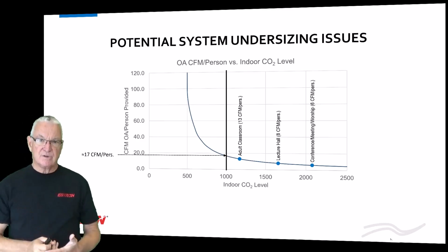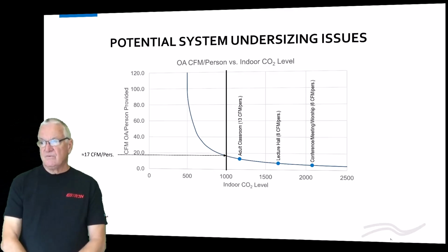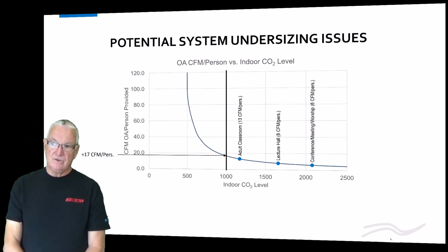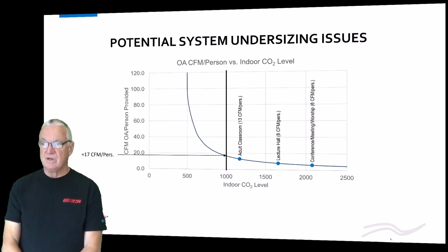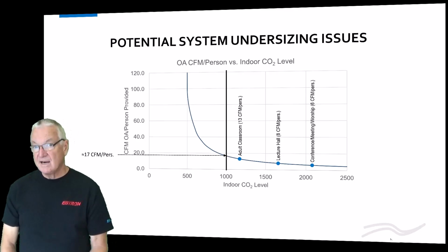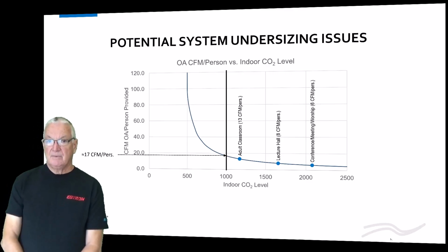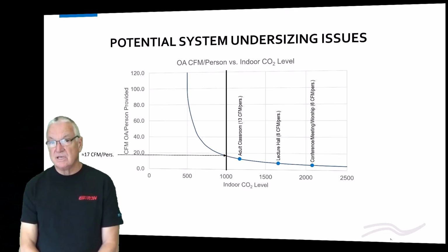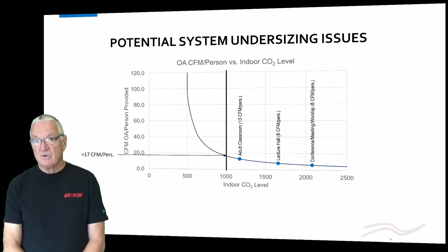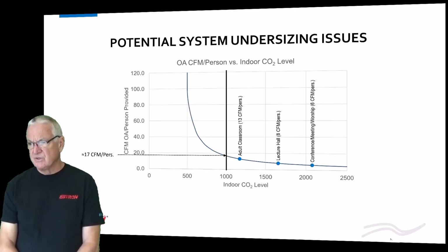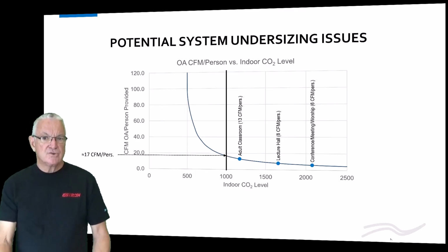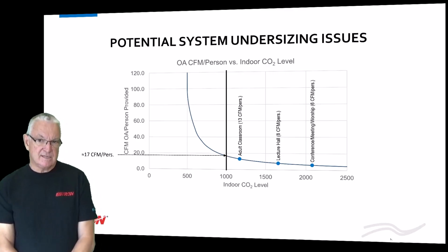You have pressurization problems. When I get into Florida or areas that aren't using economizers, where they've sized the louvers for minimum outdoor air, they've got water carryover problems. I've seen EBTRONs look like chia pets, really, because they're just getting soaking wet. I've heard people complain, hey, for some reason all the return dampers are almost closed. Of course, you're trying to bring in more outside air than you designed the system for.